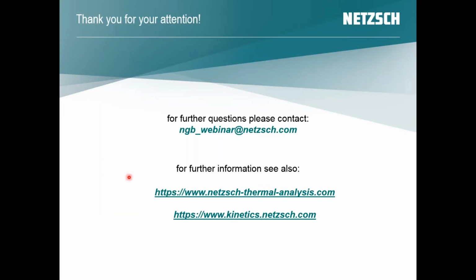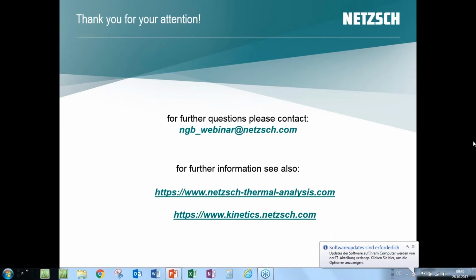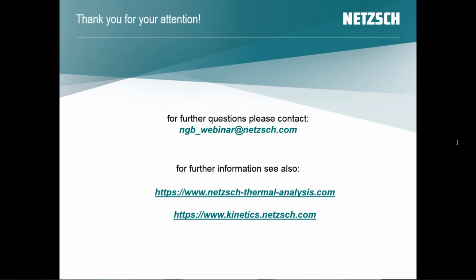Thank you. Do you have any consideration for materials which react with DTA standard material at temperatures? Example, lead oxide with aluminium standard. Of course, this is in principle one of the general questions on ceramic materials. So we need to talk, especially in the high temperature field, about material interaction. Normal materials for crucibles, so to put your sample inside of the machine, are typically aluminium oxide or platinum materials.